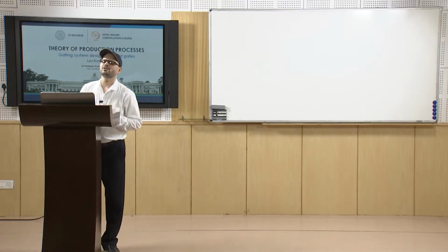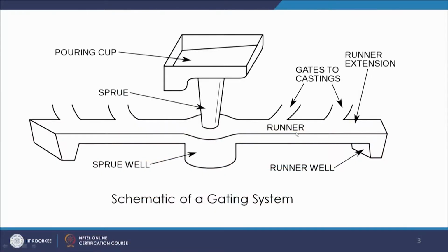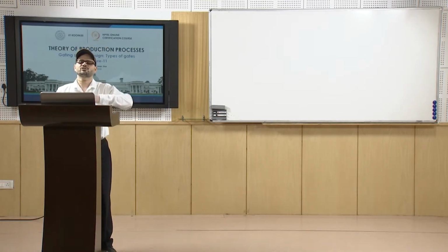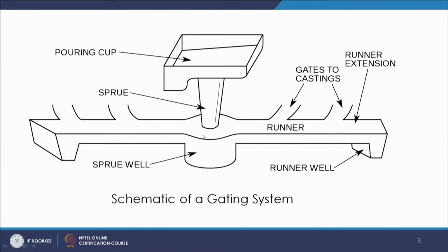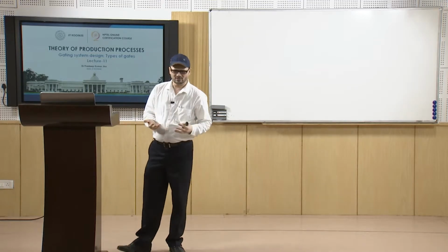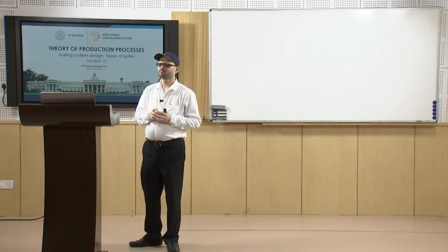Now, you ensure that you have the quiet entry of the liquid metal. For that, the metal comes to the runner, then slowly enters here. You have to see that there should not be turbulence, or aspiration because of the turbulence. For that, you make this sprue taper. That is one of the principles of making the sprue taper, so that the sprue runs full and you do not have any aspiration taking place here. Also, you proportion the runners and gates accordingly, so that the channel runs full and there is no probability of aspiration or turbulence.